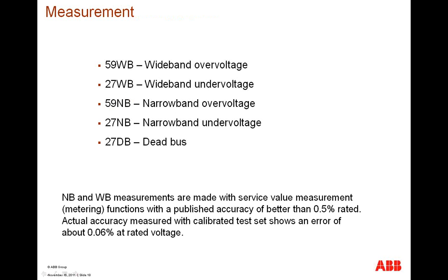So to define our measurement values, here I'm repeating what I said when we were looking at the single line. We're going to have to define the wideband over voltage, wideband under voltage, narrowband over voltage, narrowband under voltage, and a dead bus condition.